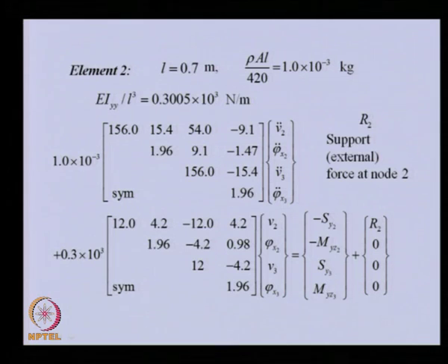Apart from this, because once we take out the shaft from the support, there will be a reaction from the shaft and a reaction from the bearing. This reaction from the bearing and this particular shear force are different. This is coming because we have cut the shaft into two pieces.